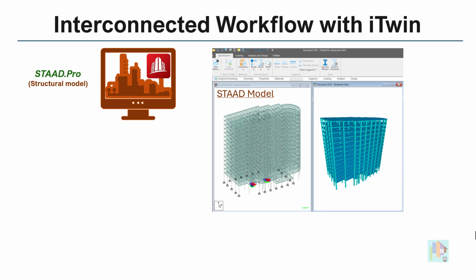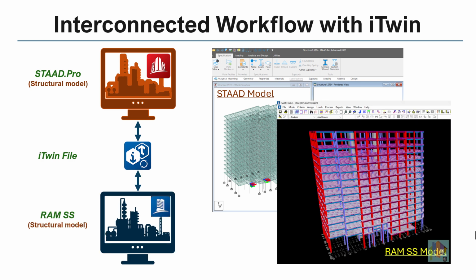Similarly, we can import any STAAD.Pro model in RAM Structural for advanced analysis. STAAD.Pro supports iTwin integration. We can create an iTwin file from STAAD. This model can be imported in RAM Structural and used for construction stage or drift analysis. That's all about modeling and analysis of a concrete building in RAM Structural.